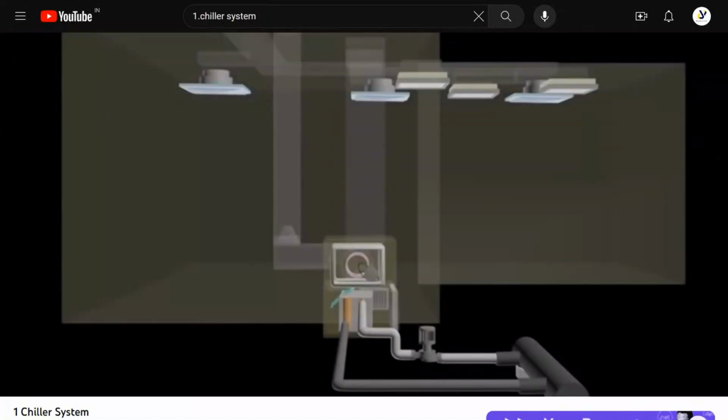For the airflow system, it is operated using an auxiliary fan which creates the air cycle from the room and mixes it with fresh air from the outside to the air handling unit and returns back to the room. The type of fan used was a centrifugal fan, powered by a motor and connected through a belt.